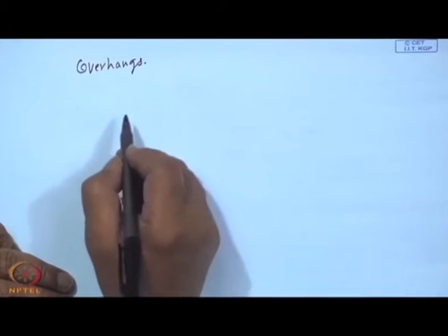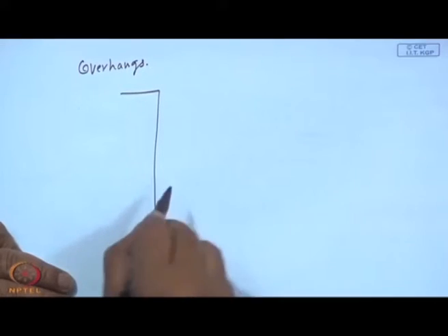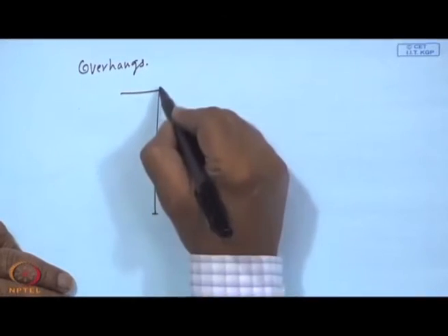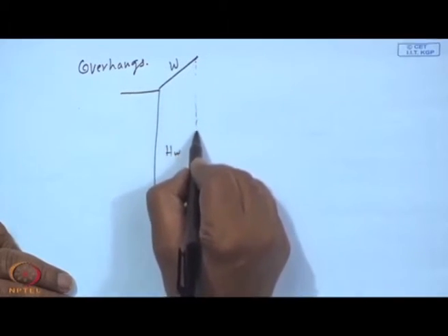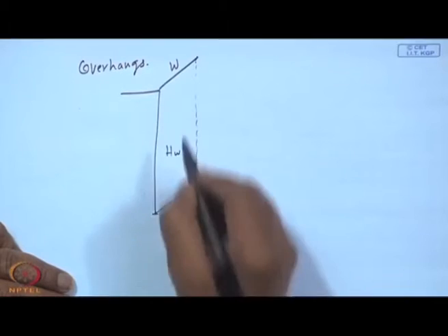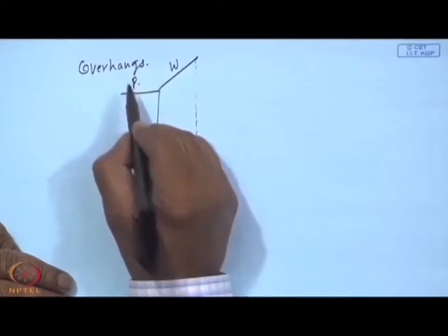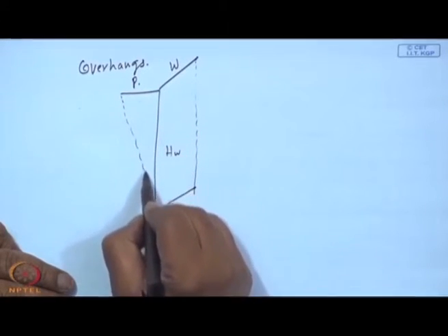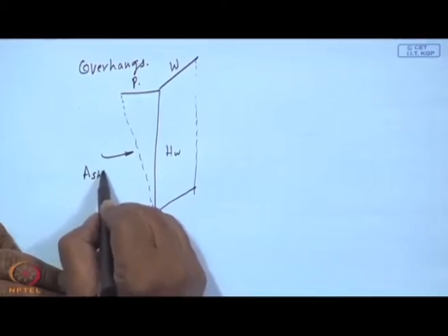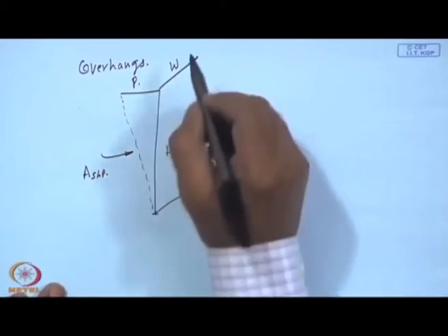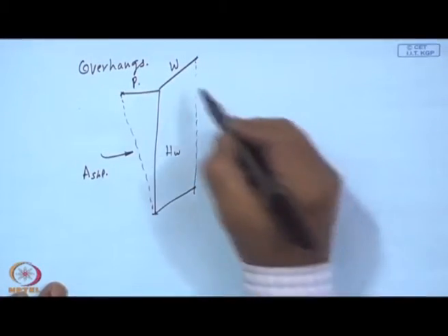In a nutshell, you can calculate the radiation received by a window of height h w and width w through an overhang of projection P by calculating the radiation entering through the shading plane, defined as the plane between the tip of the projection to the base of the window. Okay.